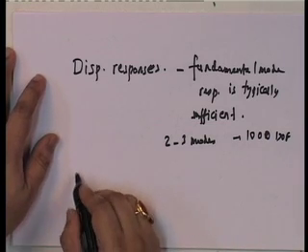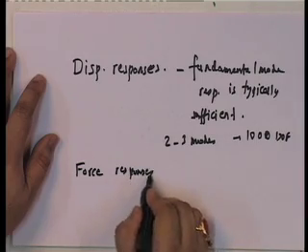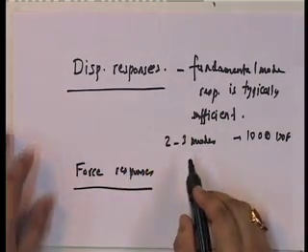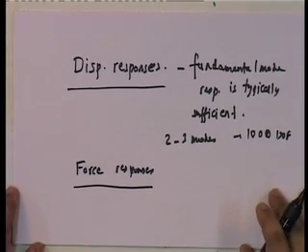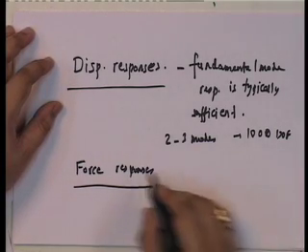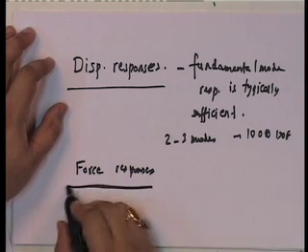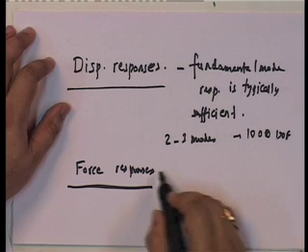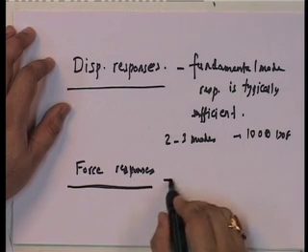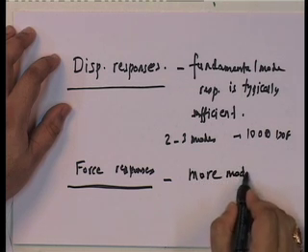But if you are looking at force responses, for example, what kind of force responses are there? For example, the base shear, or bending moment at a particular time, or story shear. If these are the things that you want to find out, then you can go ahead and do this. Force responses, you require more modes.